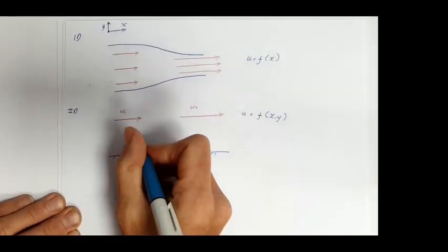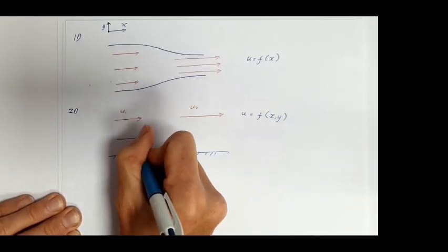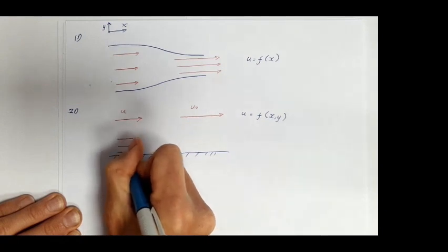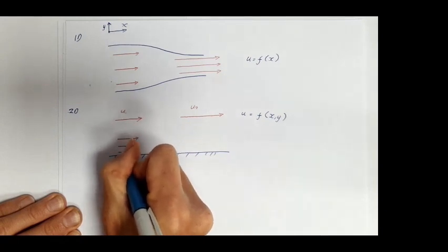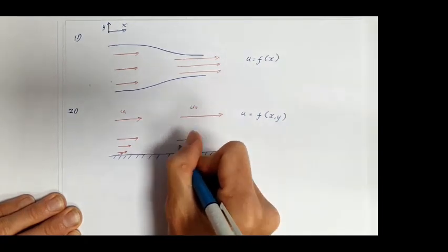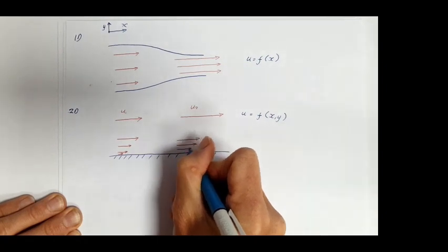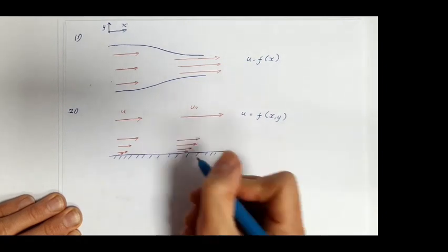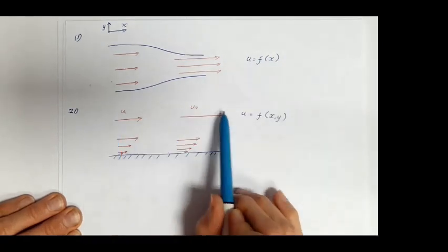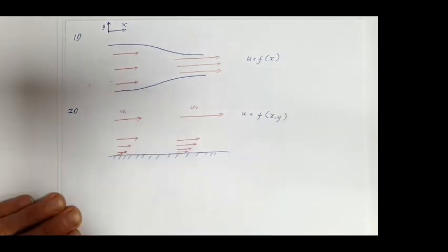As we get closer to the wall, that we were discussing a minute ago, u is approaching 0. u is going to get much smaller at the wall, due to those shearing forces inside our fluid. So we can clearly see u is a function of x, u is also a function of y. So it's two-dimensional flow.